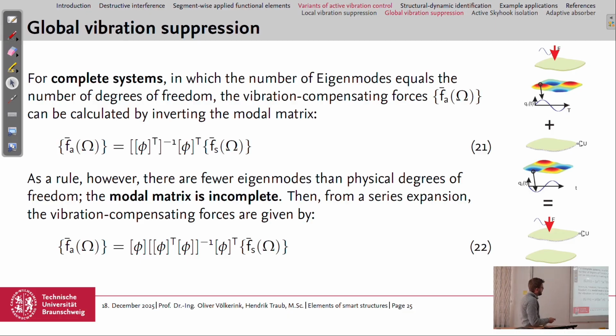And nevertheless, if we use equation 21 or 22, we now have equations to calculate the needed actuator force in terms of the frequency from the disturbance using the description of our eigenmodes.